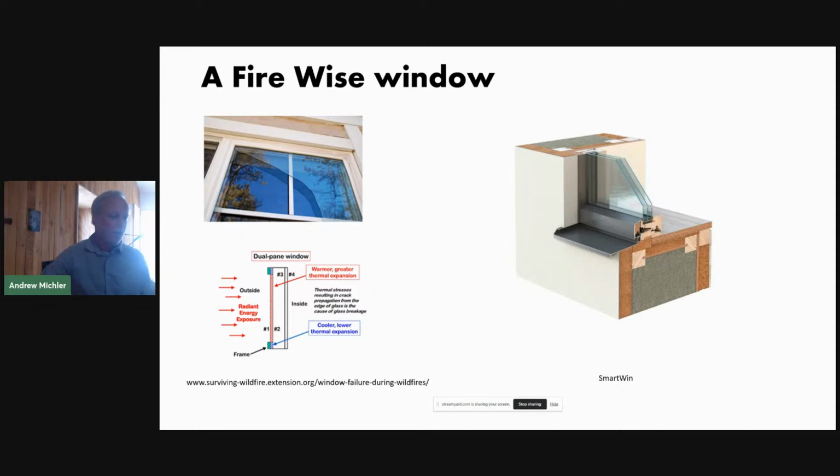Or the frames are exposed, and those frames can burn from fire. So in Passive House, one of the details for the triple pane windows is we actually bury the frames in the insulation to improve them. They're triple paned. They can be tempered. So you're significantly improving the time that the house is resilient to that fire front. So that's kind of an extra plus on top of just the overall energy and comfort side of it.